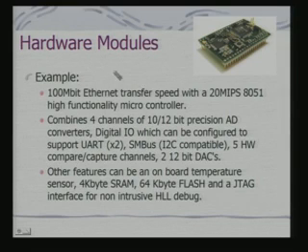That means the Ethernet protocol is provided with additional hardware as well as a microcontroller. Along with these, you have 4 channels of AD converter, digital I/O, and I2C compatible bus, then compare and capture channels. Also, it has onboard static RAM, onboard flash, and a JTAG interface for high level debug.